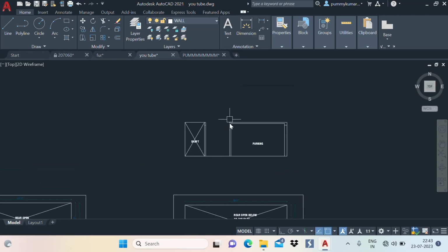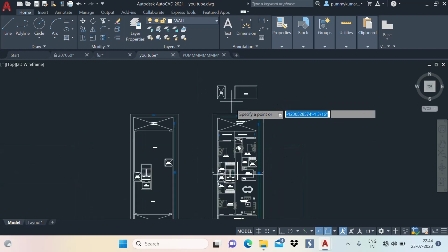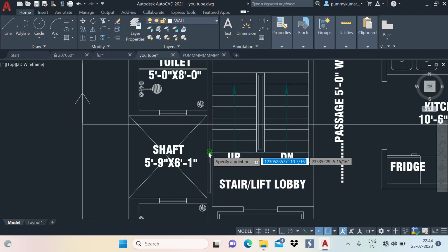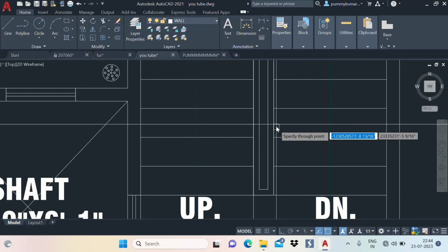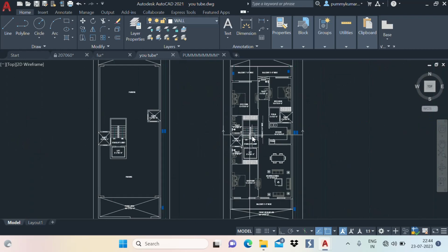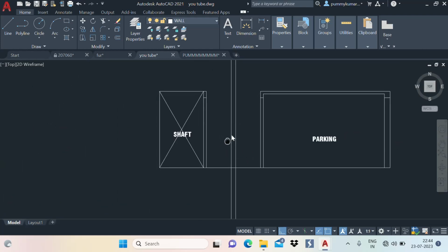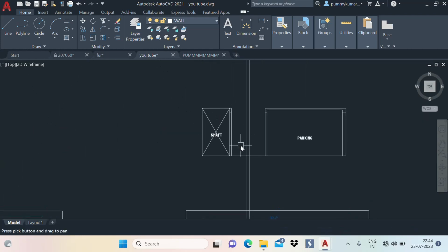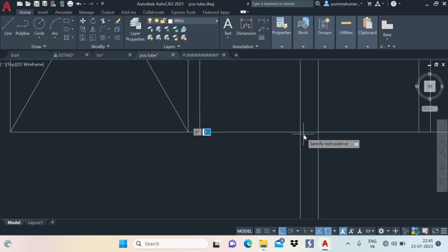After this we have to create the staircase. For creating a staircase I am again taking a construction line, whose shortcut is X enter, then I am taking it in the vertical direction, so V enter. After tracing the line, I know my riser will be 7.5 inches high, so I will make a line, L enter. And now, firstly I will make a staircase layer.